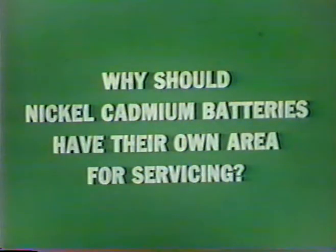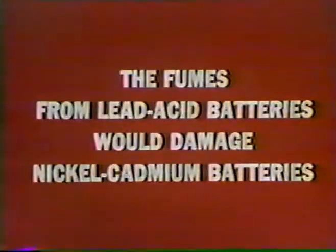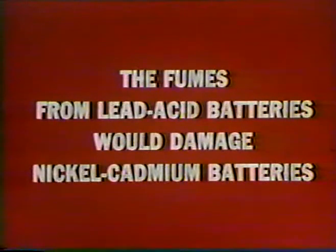Question: why should nickel-cadmium batteries have their own area for servicing? Because the fumes from lead-acid batteries will damage nickel-cadmium batteries.